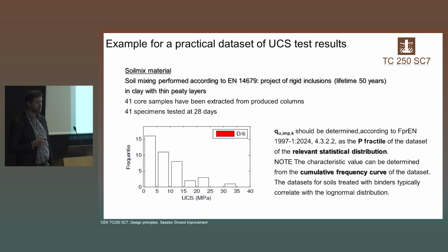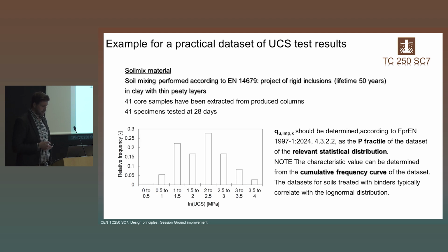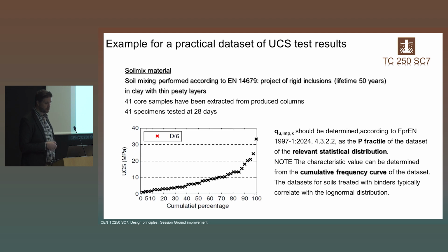We have cored 41 core samples, and the testing is at 4 weeks. We have this histogram. This is a logarithmic representation of the results. There are discussions with the customer about the perfect shape of this log normal distribution, and thus for this exercise we are using the cumulative frequency curve to avoid longer discussion with the customer.